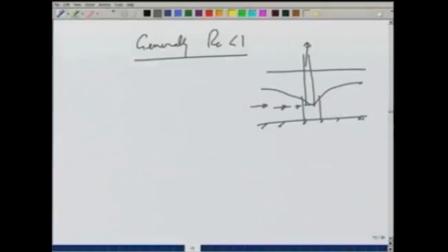So, it may not be valid in some portion here, depending on the pumping rate. If the velocity is very high, so for high pumping rates very close to the well, Darcy's law may not be applicable.